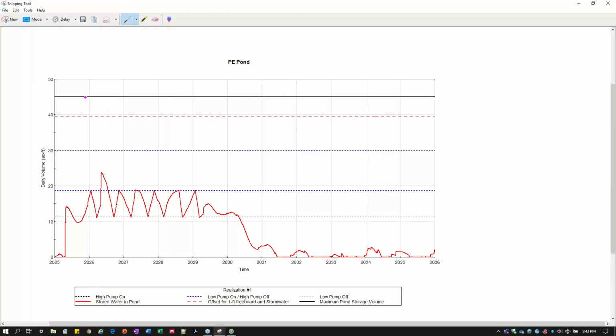And another thing that I have built in that maybe can show is I also have a couple of status elements that are just tracking, if you change the area of this pond and it overtops, you can have an interrupt. But instead of interrupting the model, what I sometimes do is I'll build in the logic to track just how many days I was over, just to see how close or far away I am from actually sizing this appropriately.